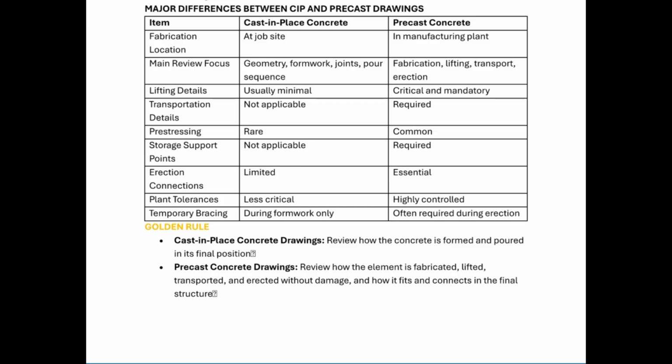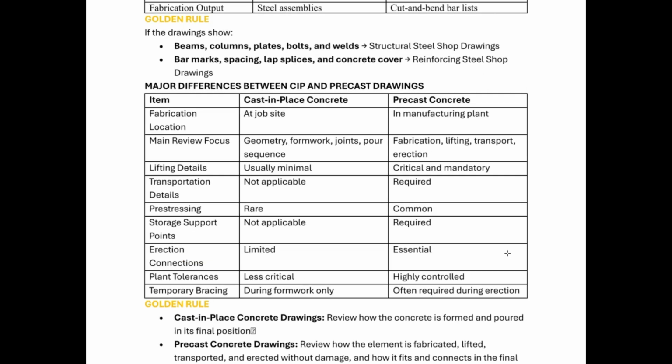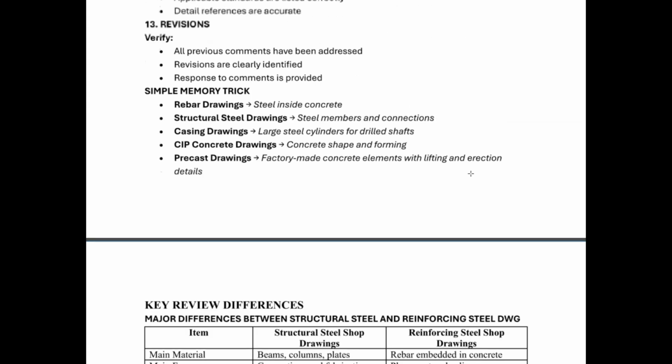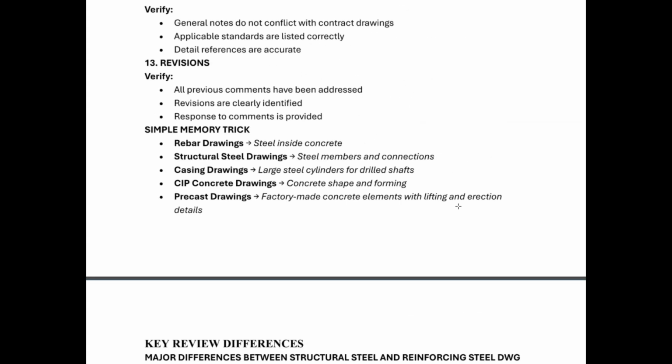For cast-in-place concrete drawings, you need to review how the concrete is formed and poured in its final position. For precast concrete drawings, review how the concrete is fabricated, lifted, transported and erected without damage, and how it fits and connects in the final structure. So we know both golden rules for cast-in-place versus precast concrete drawings. Also, we learned about the structural steel shop drawing versus the reinforcing steel shop drawing. Also, we went through the simple memory trick.